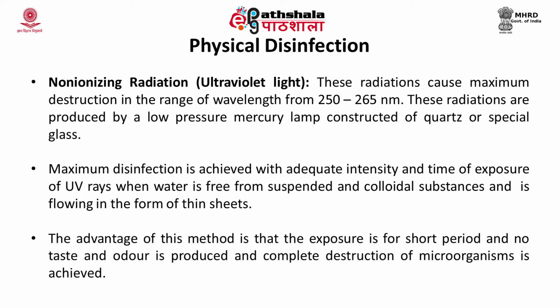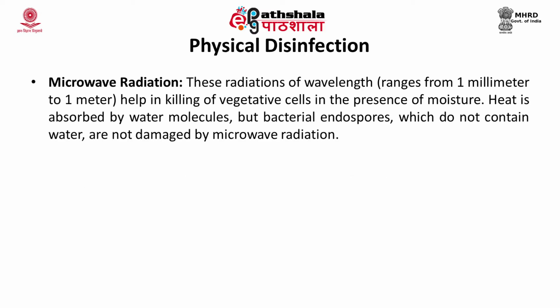The advantage of this method is that the exposure is for a short period of time, no taste and odor is produced, and complete destruction of microorganisms is achieved. Microwave radiations are also used for the disinfection process, with wavelengths ranging between 1 millimeter to 1 meter.